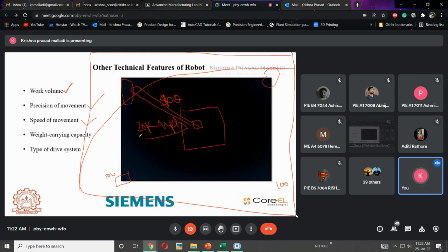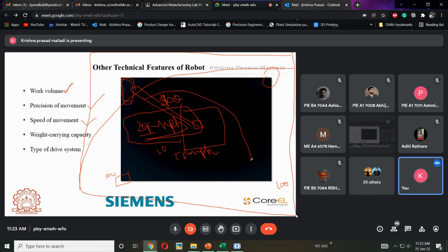So whether I need 20 kmph, 10 kmph or 5 kmph for this application, I have to search for that also. Why? Because lifting this chassis, it needs to hold this position. If the robot is designed for 20 kmph, then what will happen if I maintain 20 kmph? There will be a huge jerk, and some losses in that particular application.